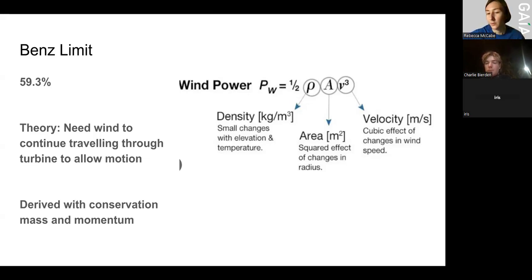Then you'd either need to use a different formula that takes that into account, that uses the distribution statistically, like the properties of the CDF of that wind power distribution, or probably the simpler way is just to calculate this power individually for each velocity in your hourly time series and then take the average at the end. You can't take the average of the velocity at the beginning.